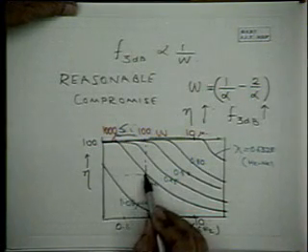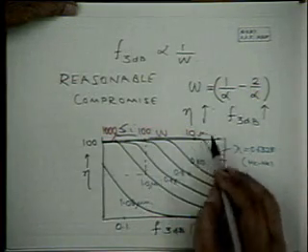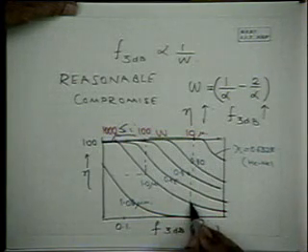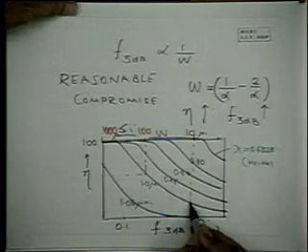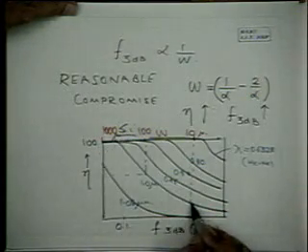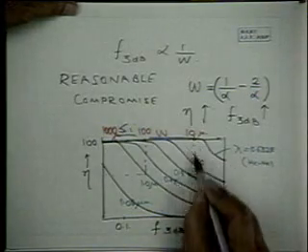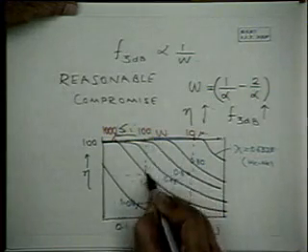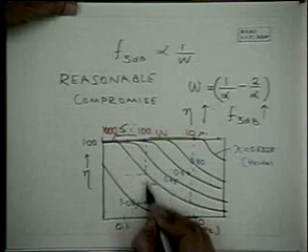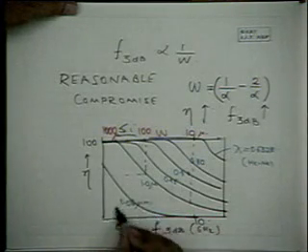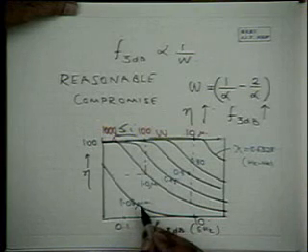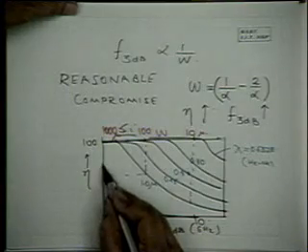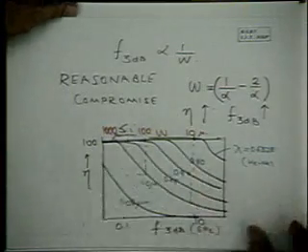whereas for the same wavelength, if you have a thinner device, the F3 dB is much larger, but the quantum efficiency is smaller. If you follow one of these lines, if W is only 10 microns, F3 dB is much larger, but the quantum efficiency is smaller. Here you have quantum efficiency larger, but F3 dB is smaller. And here 1.06 microns is the Nd-YAG laser, where optical absorption is very small. So therefore you don't get a very high quantum efficiency at all here. This is a typical silicon p-i-n diode.